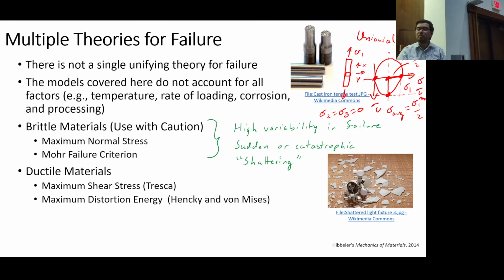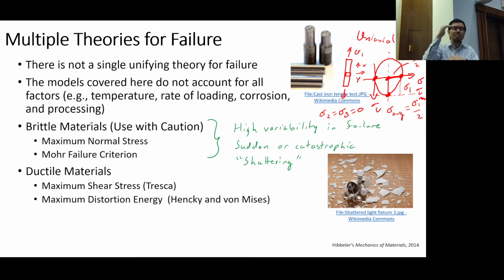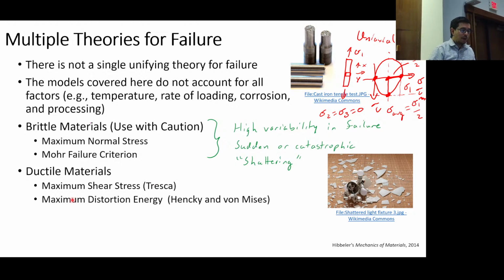And you can only hit the yield strength. That's the maximum you can put in that one direction. Why? Because that's when the material starts to yield, and we don't want that to happen in real life. So if it's a ductile material, we need to figure out what the equivalent shear stress is. And so this sigma 1, the maximum load, becomes the yield strength.